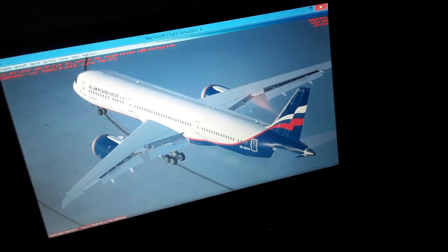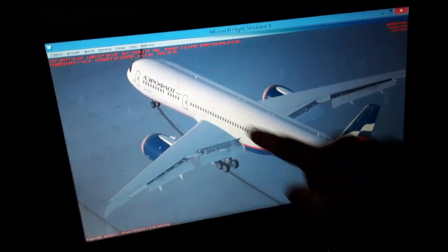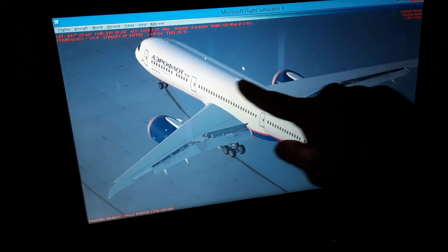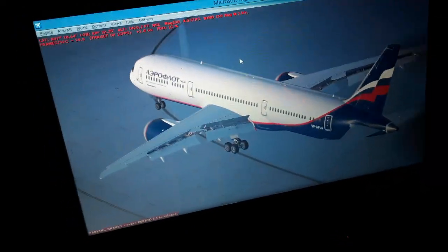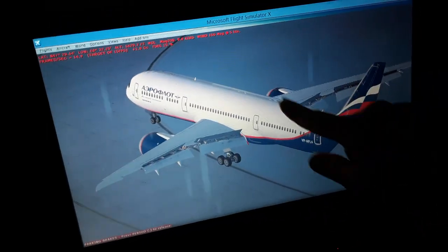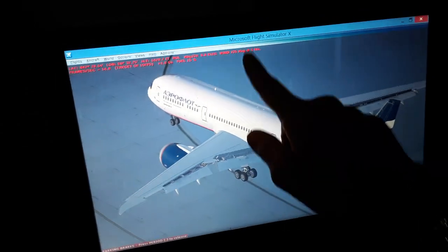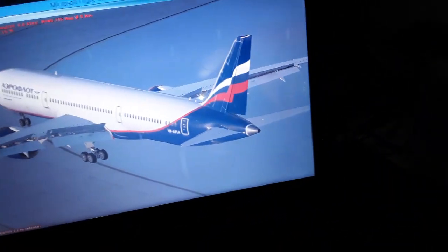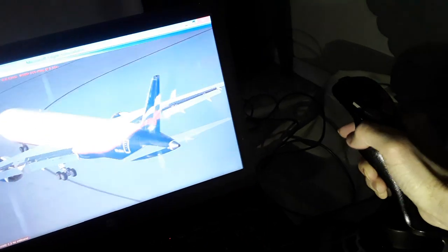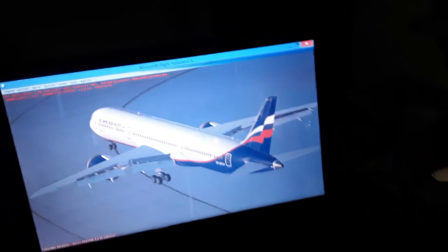So you also have the aerodynamic chord. We have the center fuel tanks over here, and the left wing tank and the right wing tank, the fuel of the aircraft over here. Where is the aerodynamic chord? And also where is the center of gravity of the aircraft, the yawing axis that traverses all this weight. So the yawing axis is doing this, it deflects the rudder right or left like this to steer the aircraft in the air. So this is the yawing axis, the vertical axis of this center of gravity.